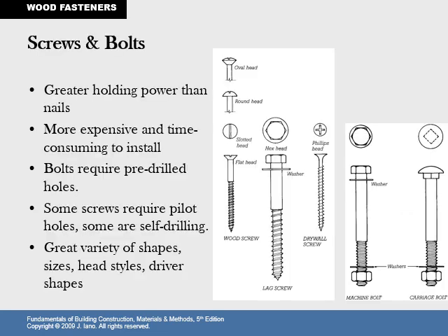Screws and bolts. Greater holding power than nails, more expensive and time consuming to install. Bolts require pre-drilled holes. Some screws require pilot holes, and some are self-drilling. There is a greater variety of shapes, sizes, head styles, and driver shapes.